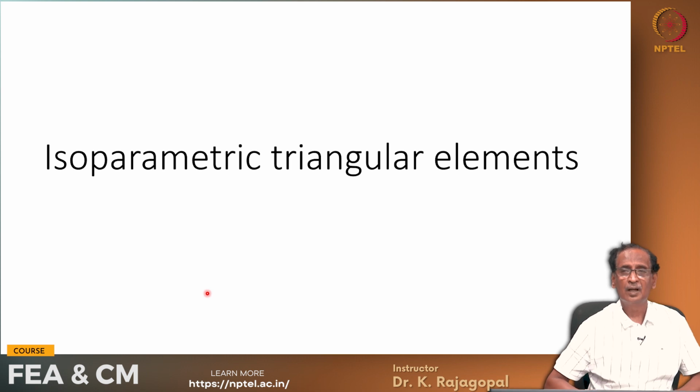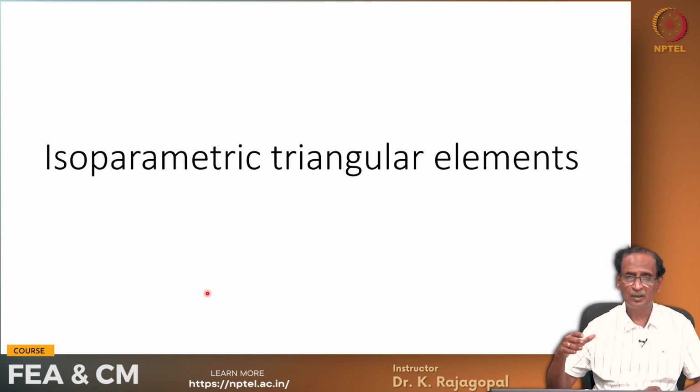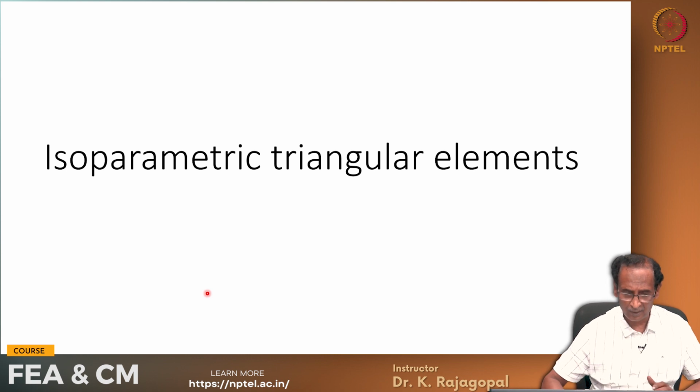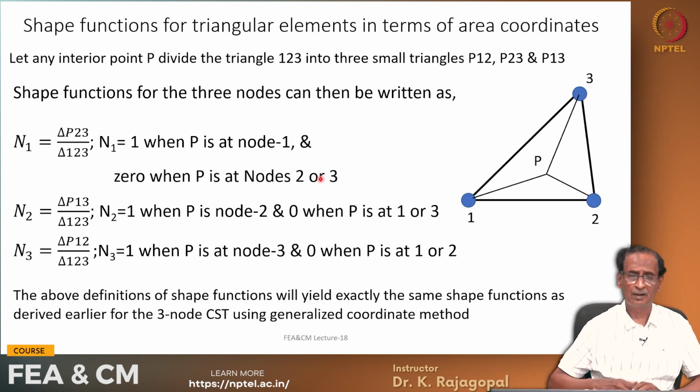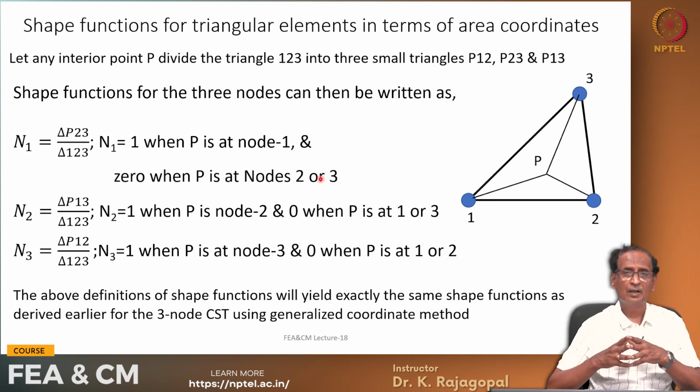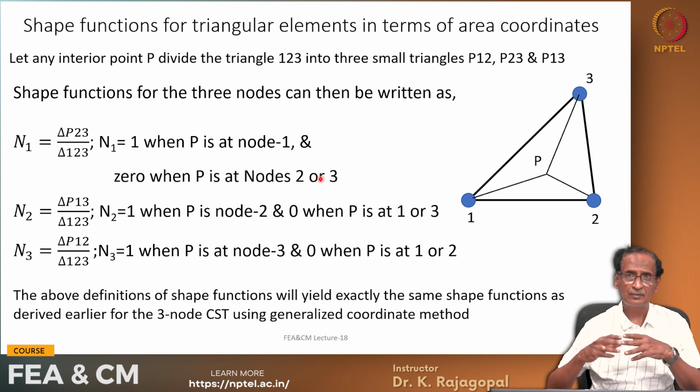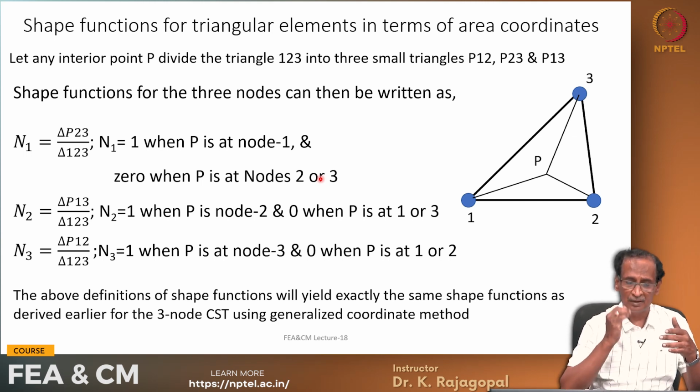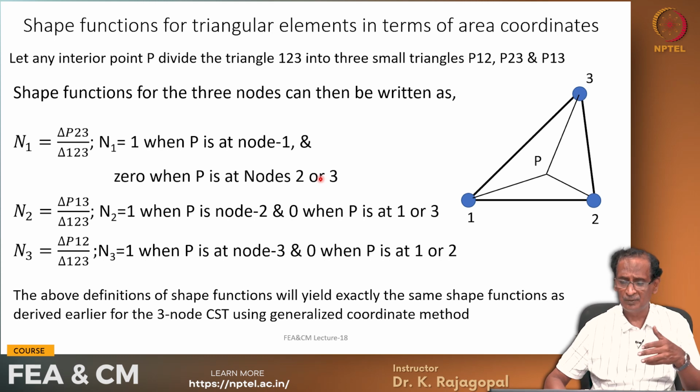See, till now we were only discussing the quadrilateral elements, and I want to briefly show you the triangular finite elements. Triangles are also very popular. As you know, the triangular elements have complete polynomials starting from 3-node triangles, 6-node and so on, and so their stability is better. Some of the modes of deformation that you see with quadrilaterals may not happen with the triangular elements.